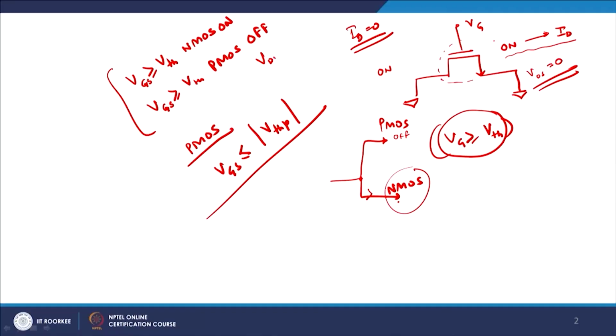So, the primary difference between NMOS and PMOS is the very basic fact that for the same amount of gate voltage given to NMOS and PMOS, like in digital logic, if VDD corresponds to 1 and VSS or ground corresponds to 0, then when you apply VDD to the gate terminal of both NMOS and PMOS, the NMOS is switched on and the PMOS goes to cutoff mode. Whenever my input equals VSS, that is 0, then my PMOS switches on and NMOS switches off, and hence the name complementary, which means that both NMOS and PMOS will never be on together.